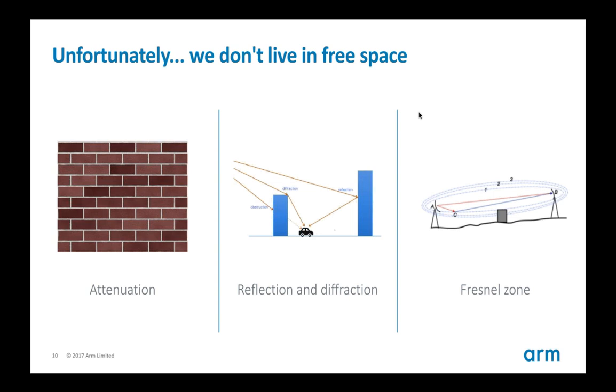And unfortunately, the Earth is a really big mass. So if you have a receiver and a transmitter both close to the ground, then the Earth will be in the Fresnel zone, and that will have a deteriorating effect on the quality of your link. So the best thing there is to always put your receiver and your transmitter on a really high location. But unfortunately, if you have a smart trash can that is 100 meters high, not a lot of people are going to throw anything in it. So it has a deteriorating effect on network quality.